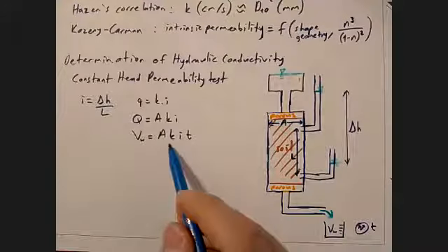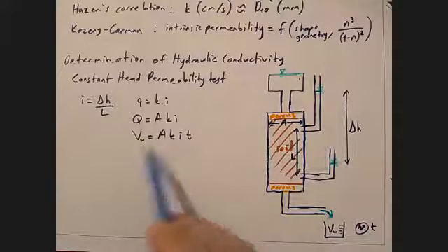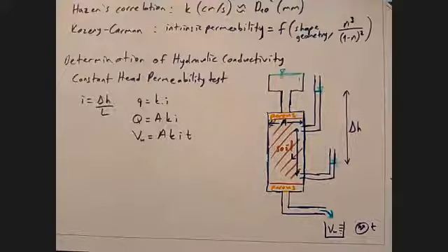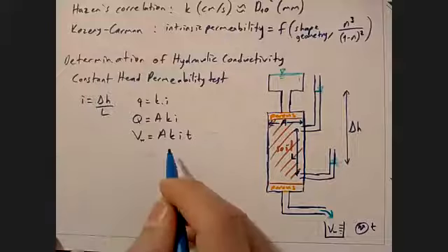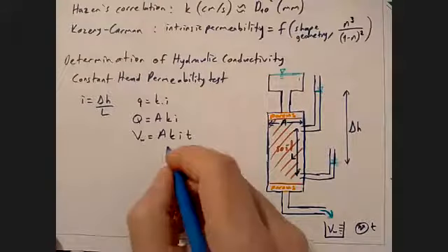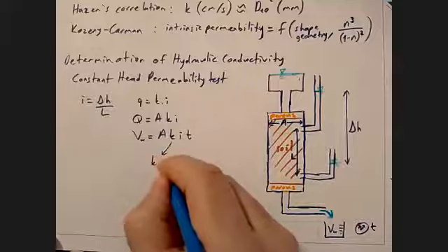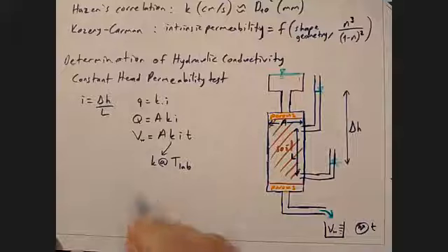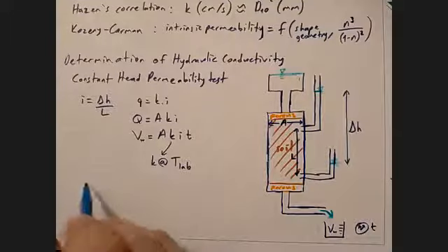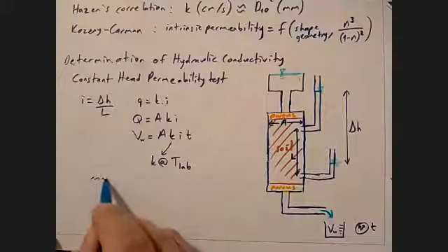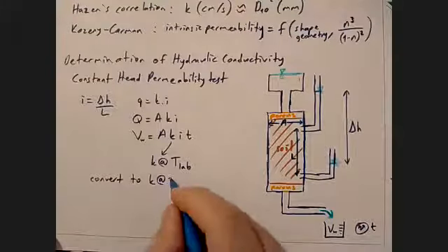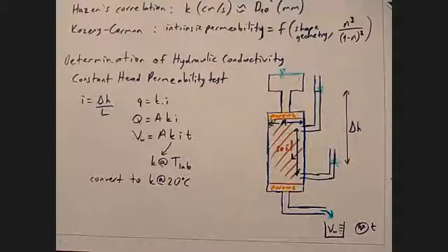Then you are able to determine or measure everything other than the hydraulic conductivity here. Of course, then this is K at lab temperature. You need to convert that to K at 20 degrees, which is the standard.